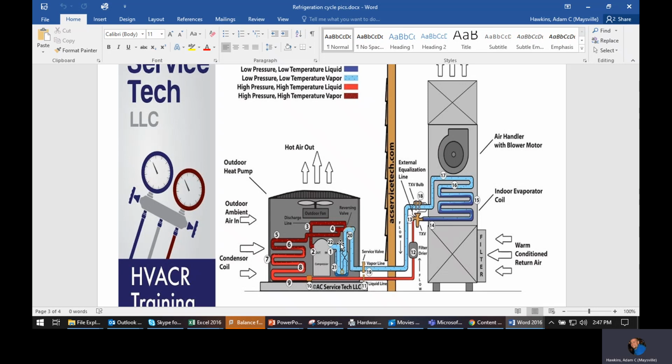What would your pressure do? Well, it said your pressure would be low. So why would your pressure be low? Your pressure on your suction and your head really is determined by getting enough air across it to actually regulate everything and set it where it's supposed to be. So if I have it set for a certain size unit with a certain amount of refrigerant at a certain amount of airflow, and then I change any of those, so I change the airflow.